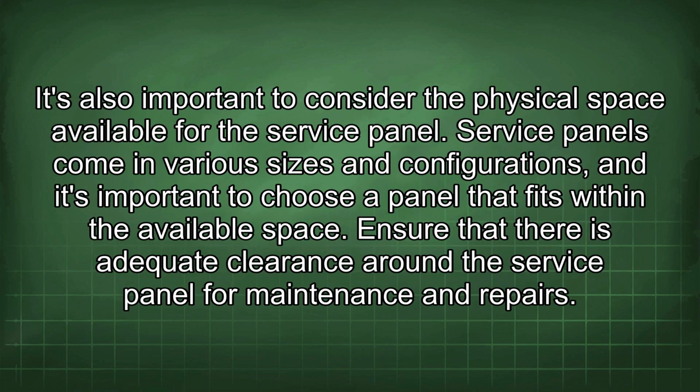It's also important to consider the physical space available for the service panel. Service panels come in various sizes and configurations, and it's important to choose a panel that fits within the available space. Ensure that there is adequate clearance around the service panel for maintenance and repairs.